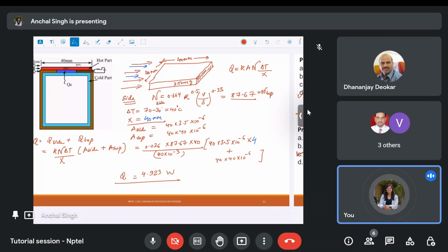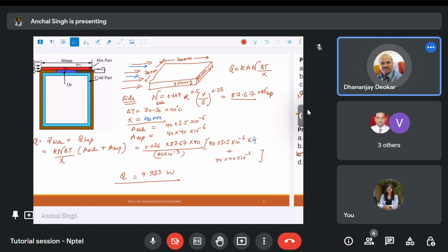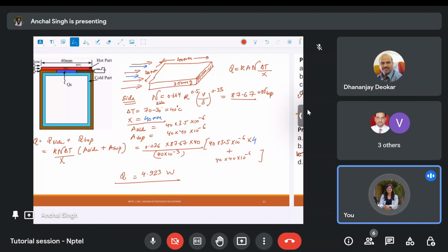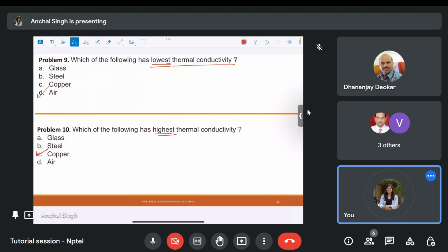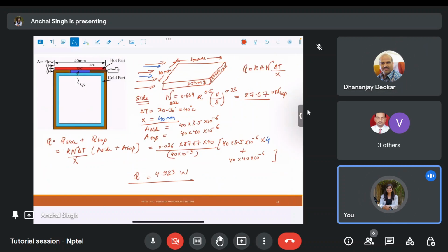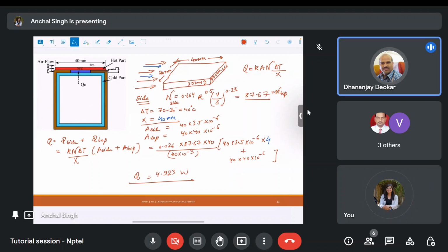Yes, definitely, because practically it won't dissipate from just one side, right? It will dissipate from all 4 sides. It's an aluminium block, but at the bottom side we do not have to consider it, only the surrounding sides as well as the top side. That is why we haven't multiplied the top by 2. We have just multiplied the sides by 4, so there will be 5 sides: 4 sides and one at the top.